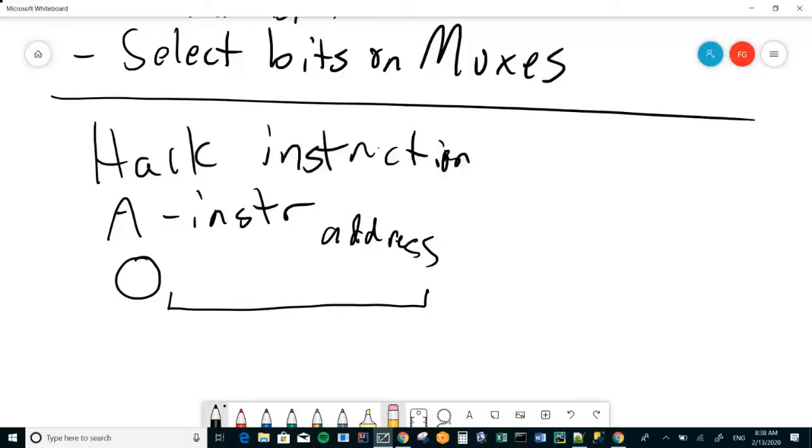If you've got a 40-bit address bus, you have a lot of addresses. Bearing in mind that 2 to the 32nd power gets you to 4 billion, 2 to the 40th power is going to be a trillion, basically, roughly. So now you got options, right? So that's another way that one can think about building an instruction. What's nice about that approach of a 64-bit wide instruction with the address built right in is now you can still do everything in one cycle.